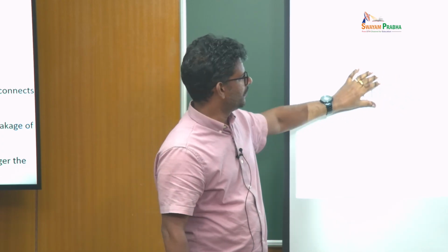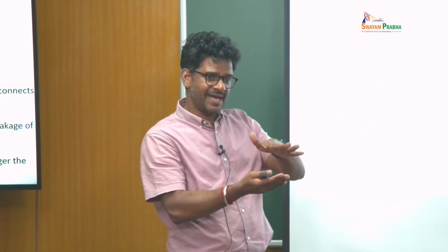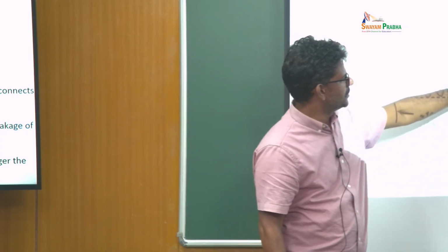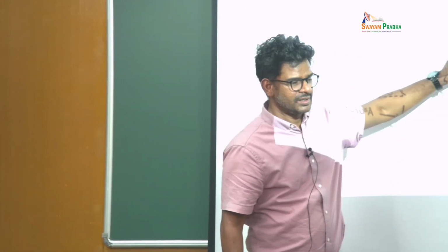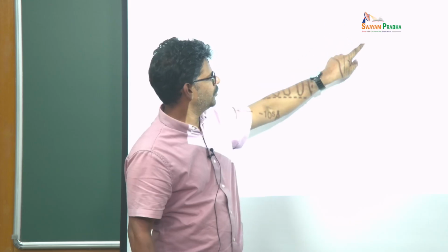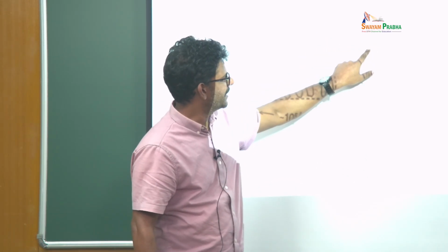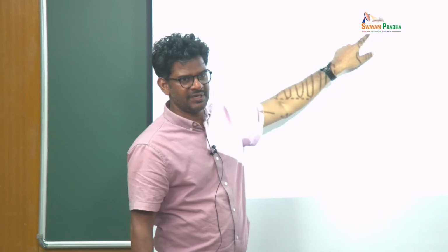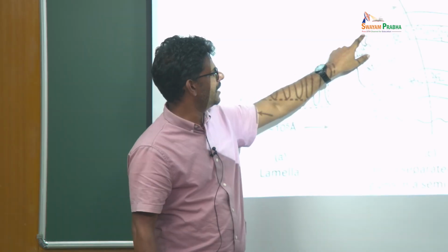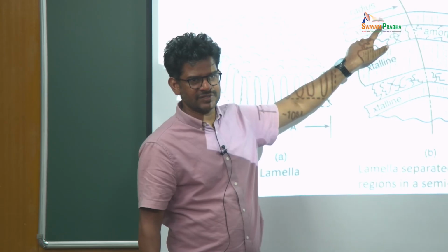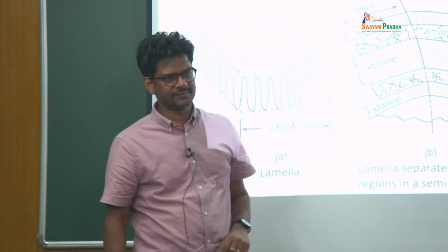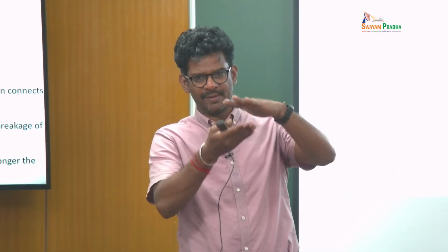Now this one can be stacked further. So, you see this is one lamellae, this is another lamellae, and between them you have some amorphous polymer. Polymer basically packs here, and extra polymer can go and become a little bit irregular, and then it can take part in this kind of crystalline arrangement in the subsequent lamellae. So, typically a crystalline polymer is basically a stack of lamellae. Between those lamellae you will have this amorphous regions.